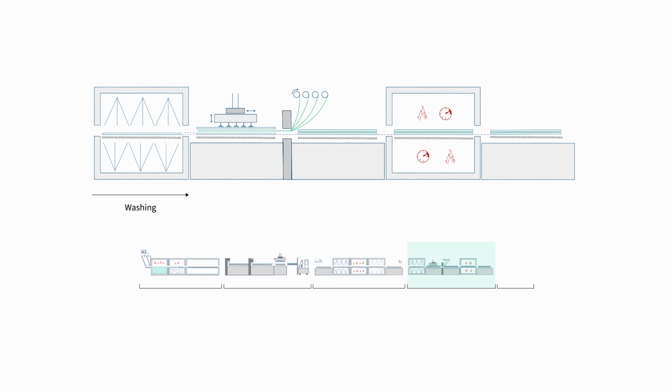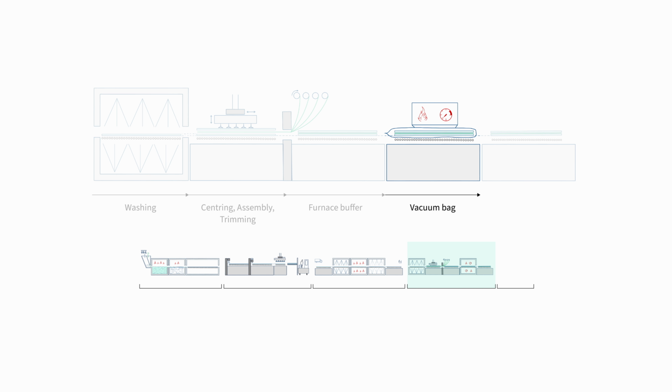The lamination process starts with washing the glass sheets or plies, which are then stacked in alternating interlayer and glass plies. The stacking phase takes place in a clean room to avoid any contamination. Heat and pressure are used, up to 12 bars and around 140 degrees C for PVB, in order to bond the sheets together. This can be performed in an autoclave or a vacuum bag setup.